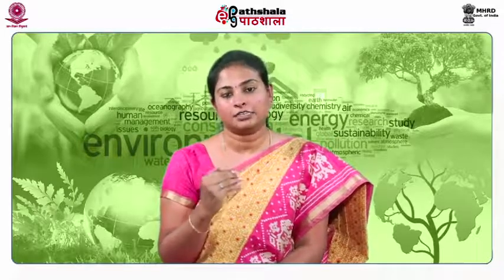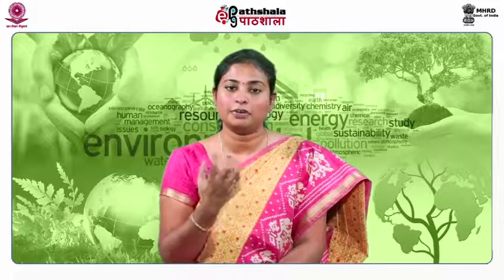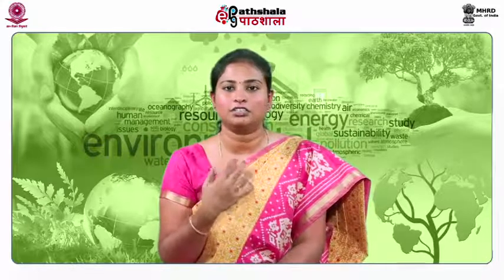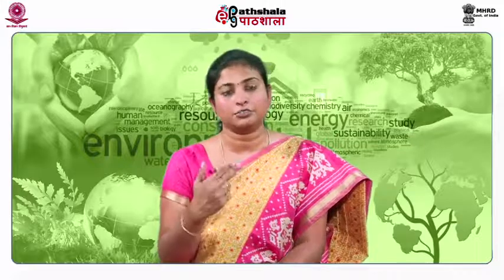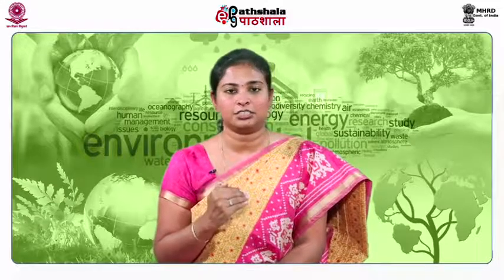So, leachate flux. The rate of leachate generation is very important because this is what is going to be used as a source to maintain the moisture inside the landfill. So, leachate recirculation should be continuously monitored and the moisture levels within the bioreactor should be continuously maintained. Also, you should be careful to avoid excess moisture because it will reduce the degradation efficiency and gas production rate.